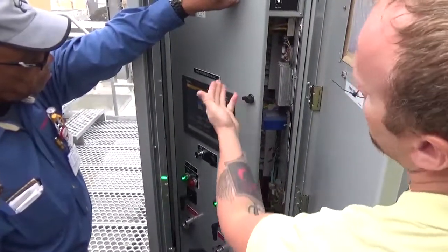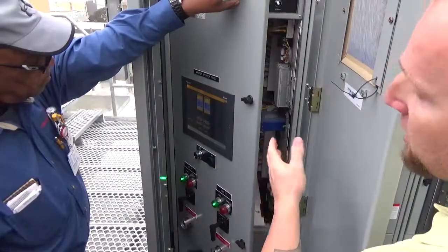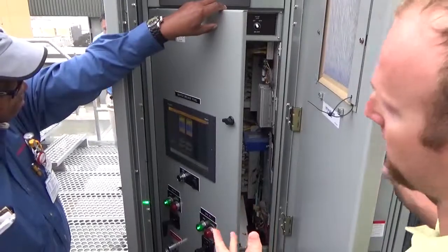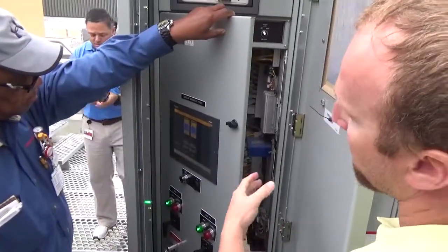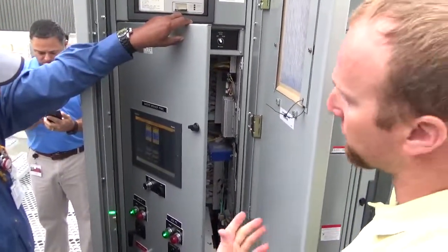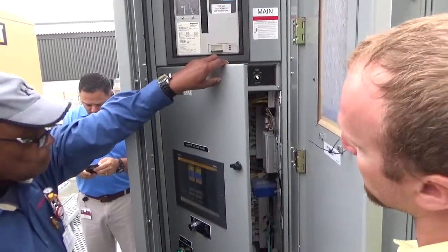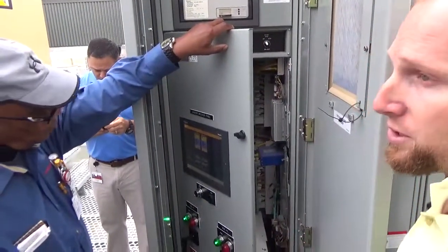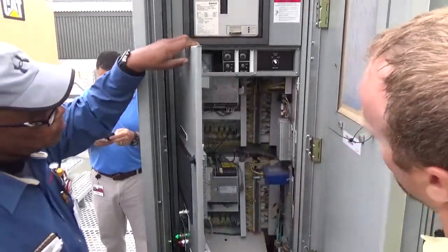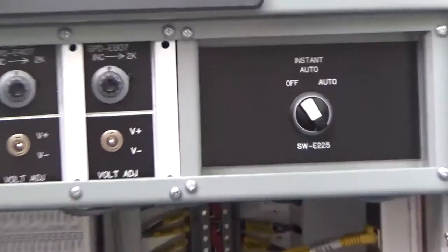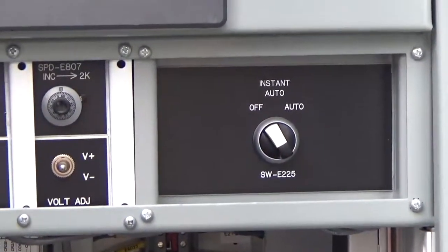Say for instance your touchscreen fails. If the touchscreen fails, you know, the world's not gonna end. That is a kind of a visual feature that's nice to have. The switchgear will still operate if your touchscreen fails. So if your touchscreen fails and you're unsure if your system is in automatic, you can come up here, hit auto, and your switchgear will still operate the way it needs to in an outage.